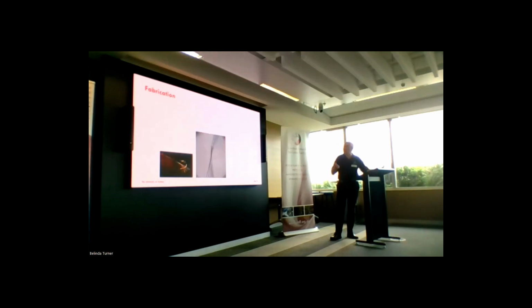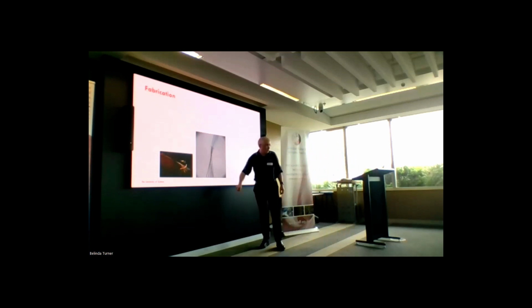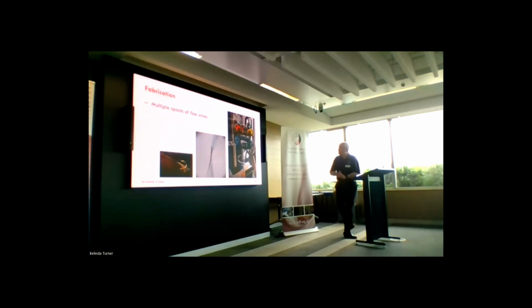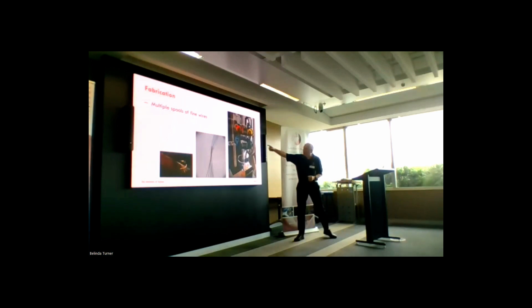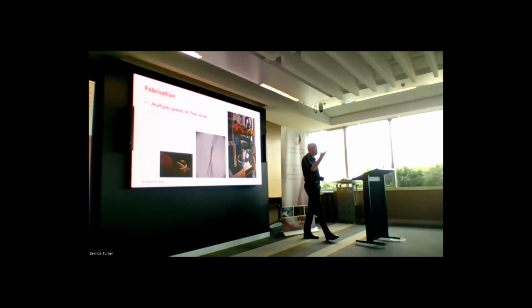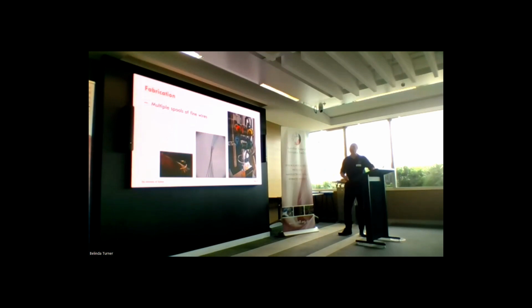drawing hard wires, and these are some pictures of the fan out with hard wires and a micrograph of hard wires coming out of the end face. How we do that, because we can't use this Taylor wire process where the metal shrinks down, is we start with very fine wires on spools, a guide, and then they go into the top of the preform. And as the preform shrinks in the neck down region, it collapses onto the wire, grabs it and pulls it through. And that works